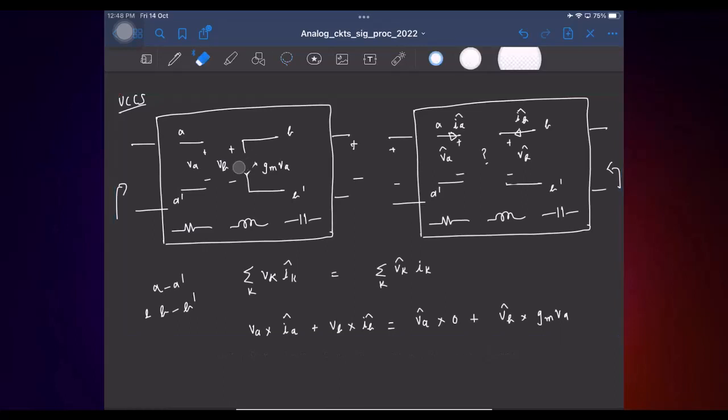So now here we have a voltage controlled voltage source. Say the ratio is K. Here we'll have to find what we need to put, right? So again we'll do the same thing. The voltage here VA times the current here IA hat is there. Second is the voltage in this branch, which is K times VA times the current flowing here IB hat.